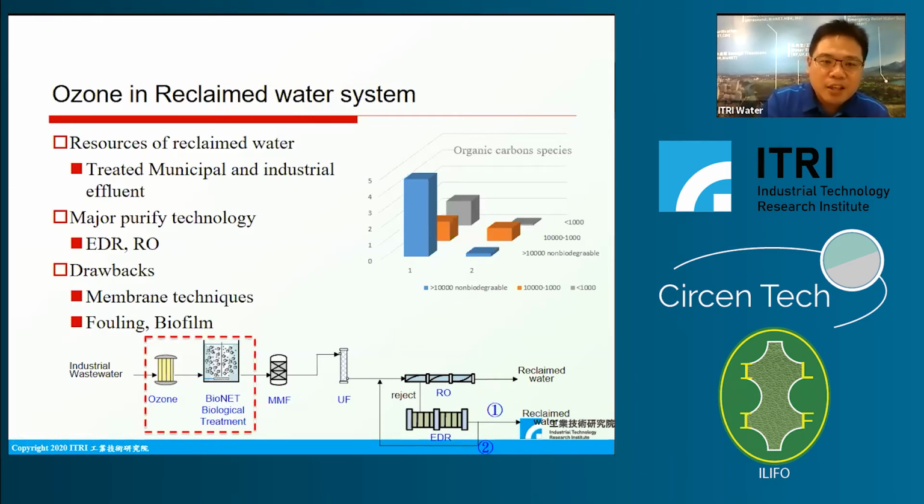But the COD released from the secondary treatment cannot be easily decomposed by the biological system. So here, we first introduce using the ozone as a pre-treatment system to decompose this kind of the macromolecules into small molecules and enhance the biodegradation.